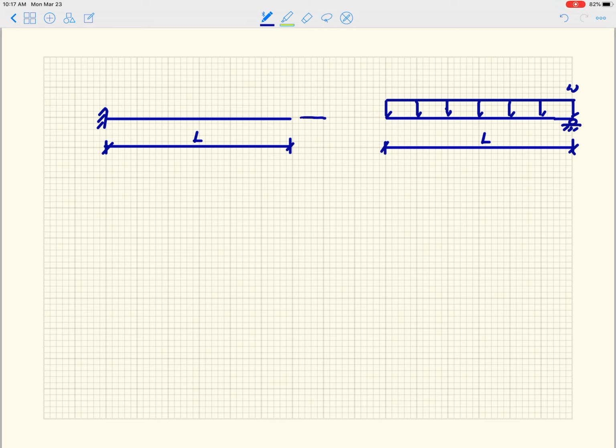So here I'm going to apply the axial forces pointing at one another, and I'm going to apply my vertical forces in that direction. So this we're going to call QY, and this QX. Q is really an internal action. Again, there's only two unknowns here, because as soon as I solve for QY and QX on the left-hand portion of the structure, I'm just going to flip it over and apply it to the right-hand portion, and vice versa.